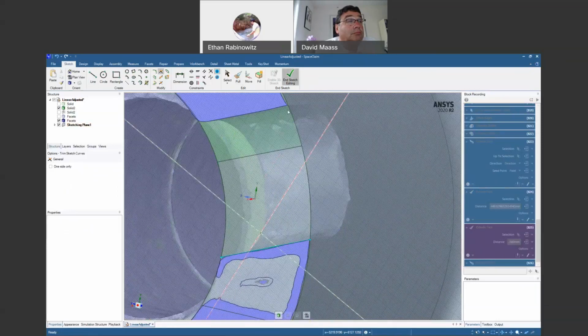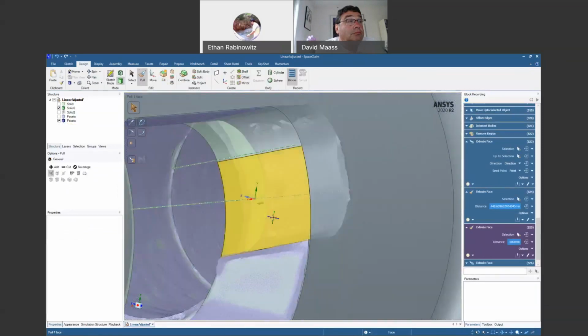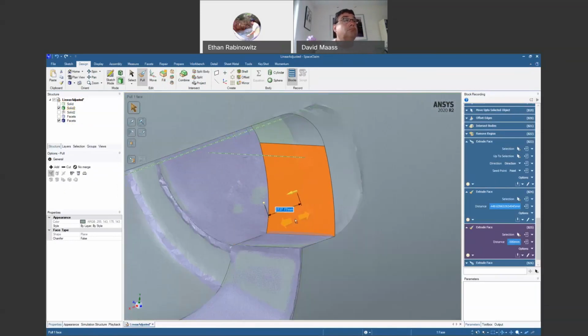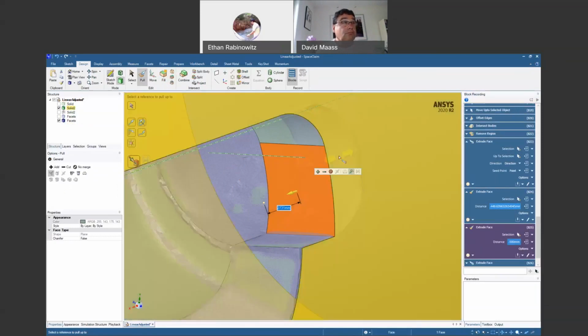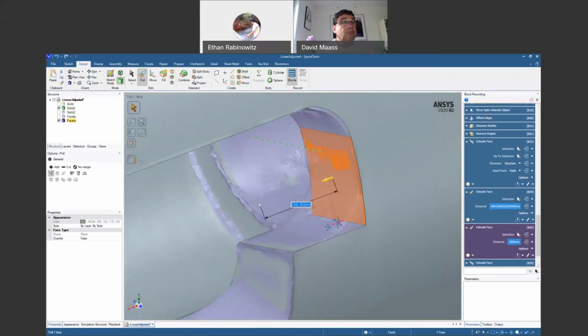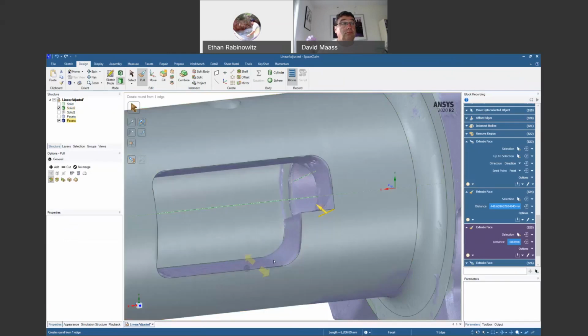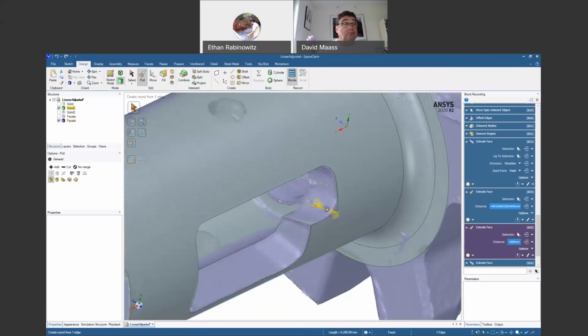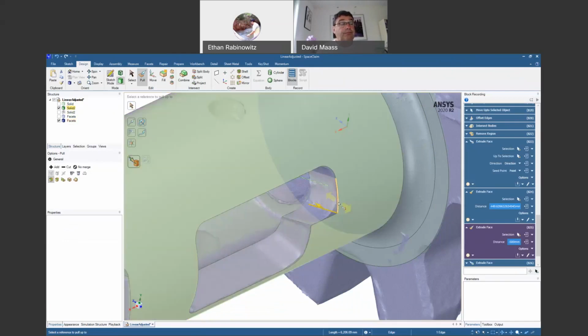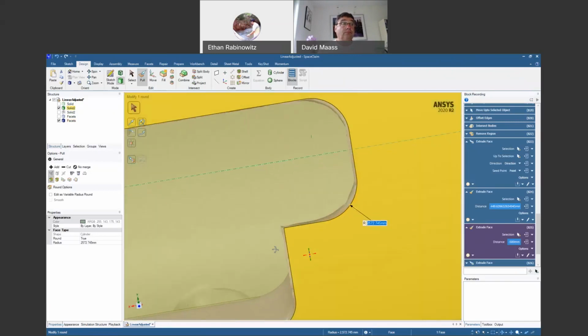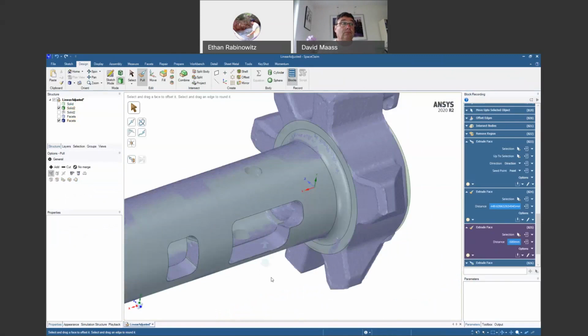And when we now go back into 3D, that splits that face up. So just sketching across that face will split it up. And now I can just pull it back like we did before. But in this case, I'll then say, up to, and grab one of the facets there. And here I want to make this edge round. I don't want to pick facets again, because if this is a machine part, all of these corner rounds are essentially the same size based on the end mill. So I just want to make sure they're the same. So I'll just say, pull that one up to, and I'll make sure that I scroll my wheel to pick the CAD face. And then those will be the same size. And this one looks like it had a sharp edge or something like that. So now that piece there is done.